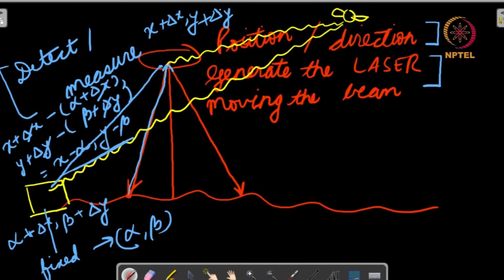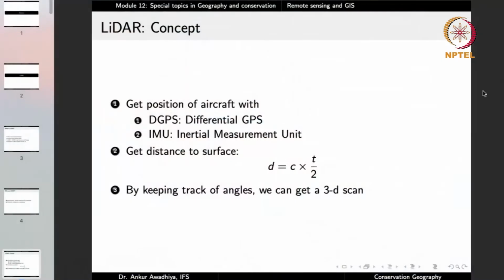So we take the measurements at two locations. One is the location of the aircraft and the second is the location of a ground point or a fixed station. Do a subtraction of both of these, and because the errors are the same in the measurement in the aircraft and in the measurement on the ground, these errors will get cancelled away and we can figure out the exact location of the aircraft. So that is the utility of differential GPS.